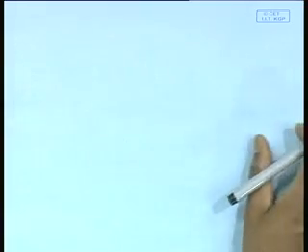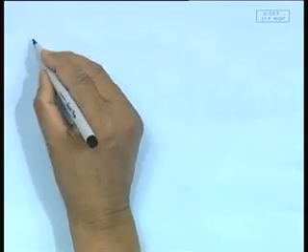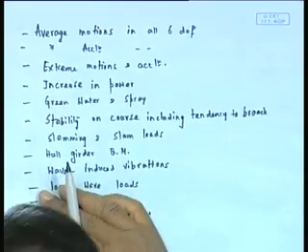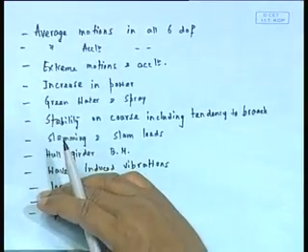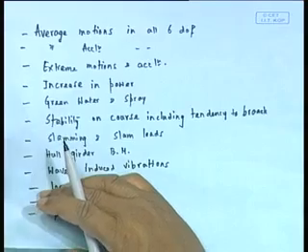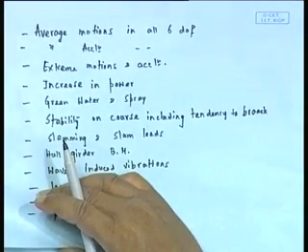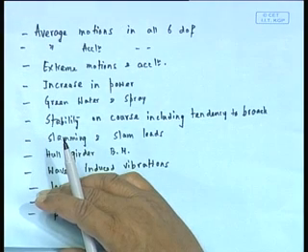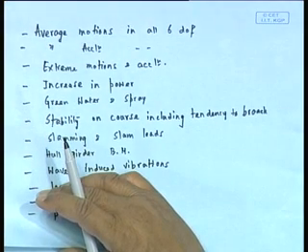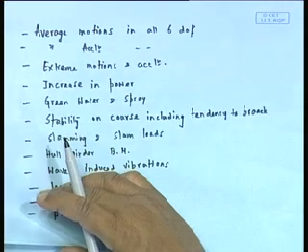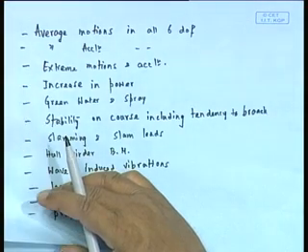Let me give you an example of such a criterion, just to have an understanding. Once again, these are the factors that affect. What do we require? We require to assess a design, or consider seakeeping aspects in design, even in the initial stages. So I must have a criterion specifying that my design should not exceed so and so; for example, acceleration must not be more than, say, 0.2 g.